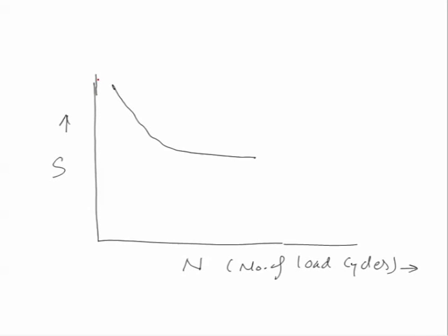It is common to use S for the stress amplitude, and that indicates the average of the stress range, that is, S stands for sigma max, maximum stress, minus minimum stress, divided by 2. So, it is half of the stress range. It can be maximum stress also. So, there are different ways through which S can be in different forms: stress amplitude, stress range, or the maximum stress.